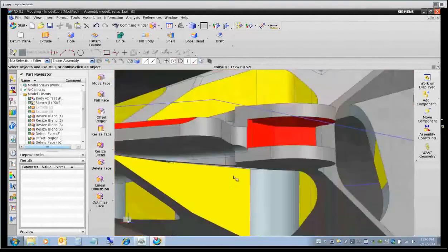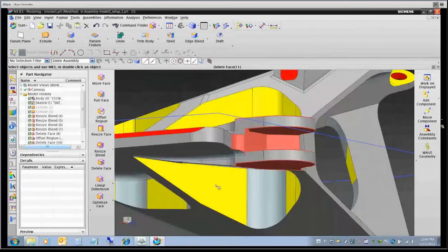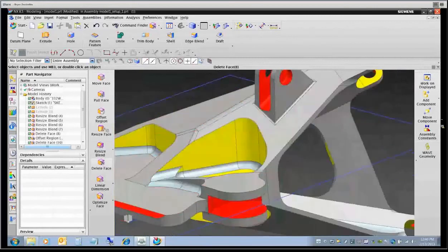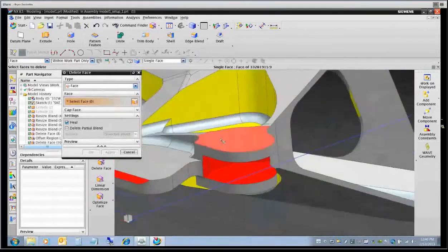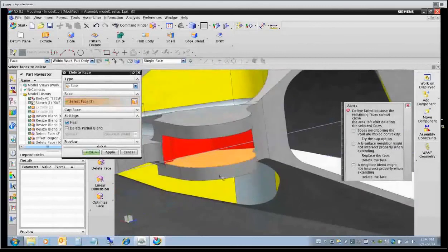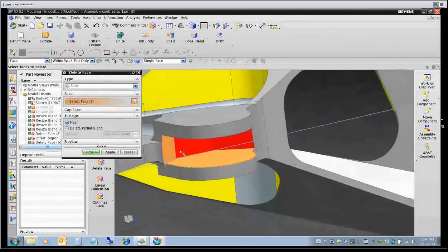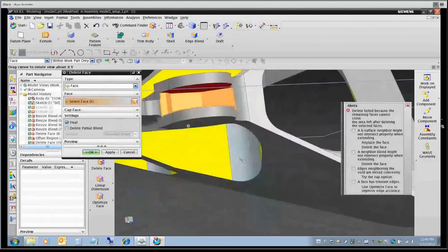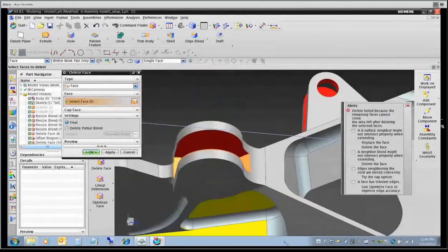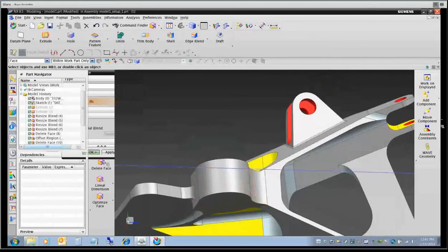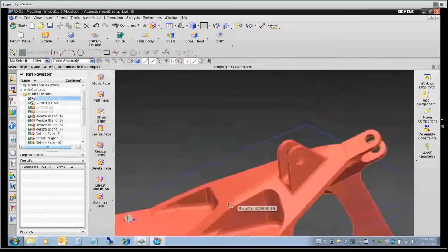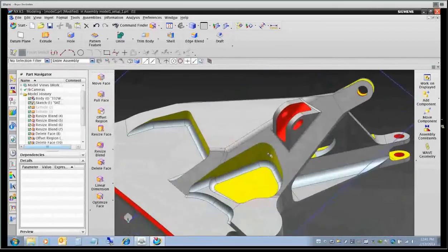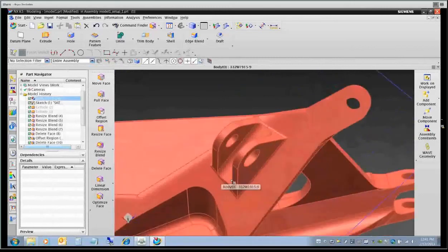Now we'll go back into this face here, and you may want to go in and remove all of this area inside the part. So in other words, it'll create this back effectively as maybe a casting would have looked like for this part. And again, it's just going to make this back as a solid, so it's not a series of scarred surfaces. I'll show you this other one up here real quick and show you how to do an offset to both of those guys.